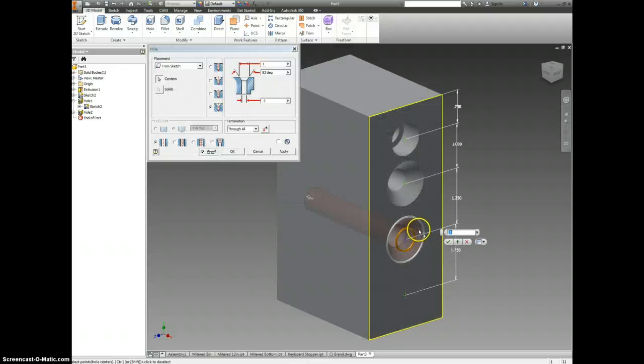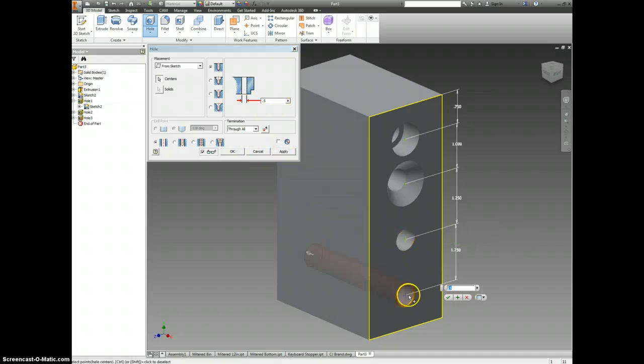Your next point is a regular clearance hole with a diameter of a 1/2 inch. And your last hole here is another counterbore. The counterbore has a diameter of 0.375 and a depth of a 1/4 inch, and the through diameter, I guess it's not going all the way through, but the other diameter is 0.25, and that is a depth of 1 inch.